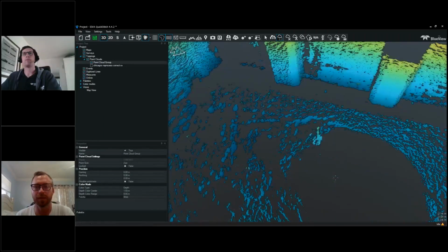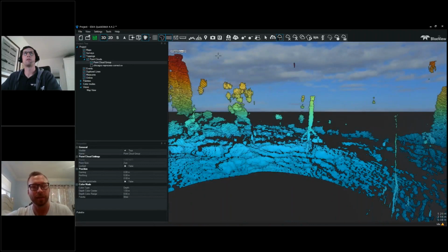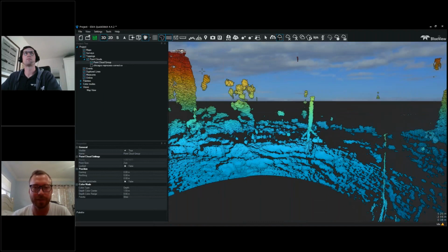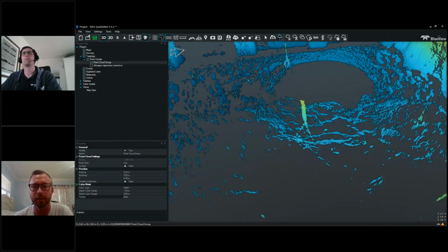If you followed our previous webinars, that reference target that Tyler's talking about is an artificial target that's placed in there to help with registration from point cloud to point cloud and make it a more accurate registration, having a known target in those structures. Right.